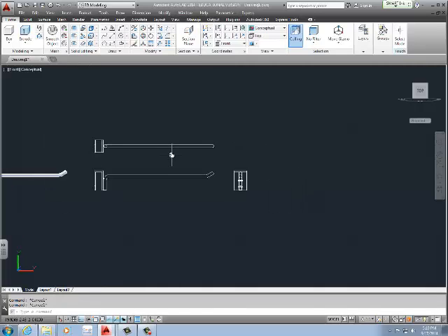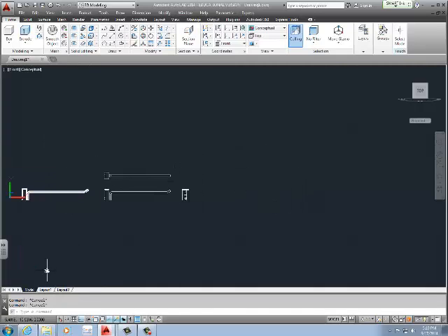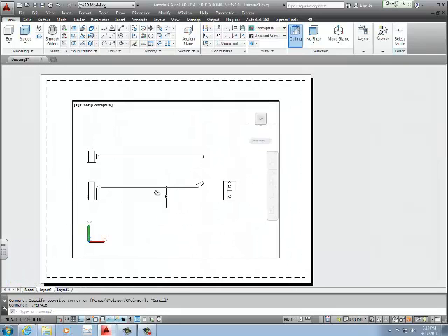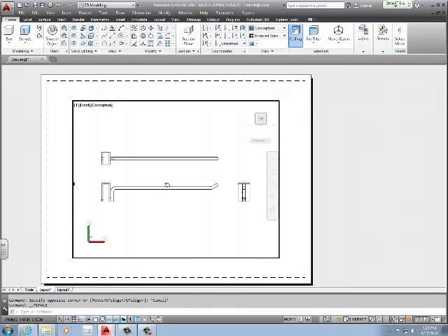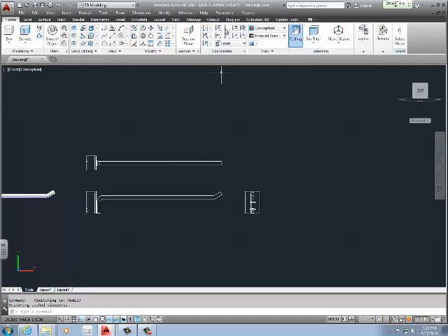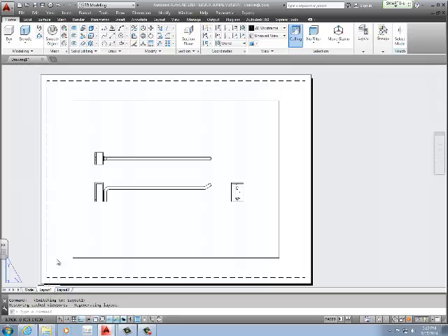What you can do is type in calc, and it gives you a very nice calculator. Now, if I had my title block, which I mistakenly did not, I would use a viewport to zoom into this. You could add dimensions in your model space using quick calc, or you can do it in your paper space. I recommend doing all dimensions in the model space to find out the exact size. If you're doing paper space and you edit something here, it doesn't change, you might not catch it, and you risk not having all the exact dimensions you had before, or they got moved, and so forth.